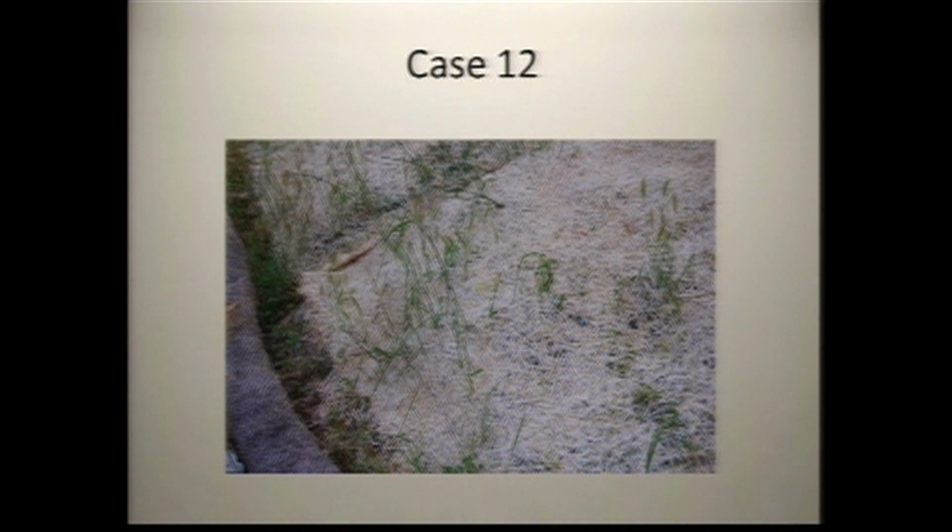And it's because the contractor that put it down only stapled the edges of the blanket. You need to have a staple every 3/4 of a square yard. Like we talked about, it has to be in contact with the soil for it to work. So it started getting some vegetation, pushed all the blanket up, and it rolled underneath the blanket.